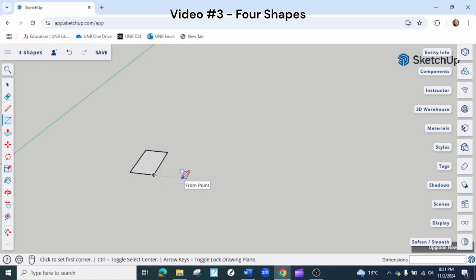Our new shape will be a 3-inch by 3-inch square. So you can try it if you want on your own, or keep watching right now if you want to do it with me. With our rectangle tool, R, we are going to click and release. It's now in edit mode, and we release the mouse, come over to our computer with our right hand, and go 3 inches by 3 inches. So you look down in the bottom right corner, it should say 3 quotation, comma, 3 quotation, no spaces, and hit enter. And now we have a 3-inch by 3-inch square.